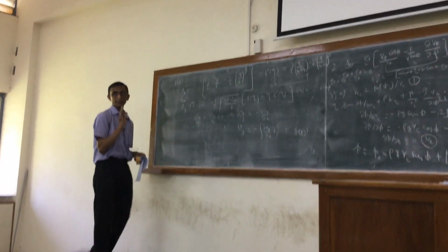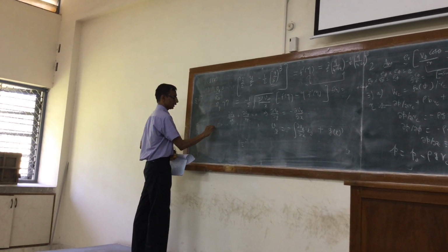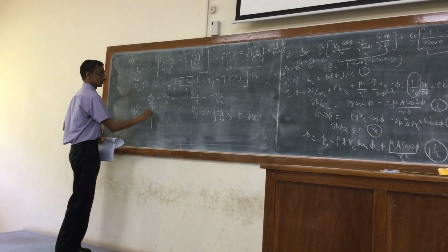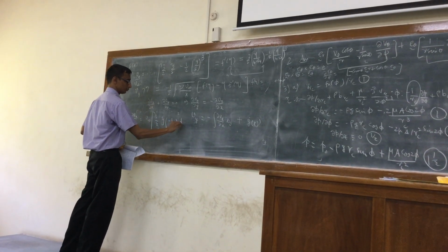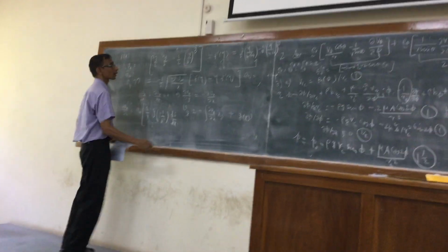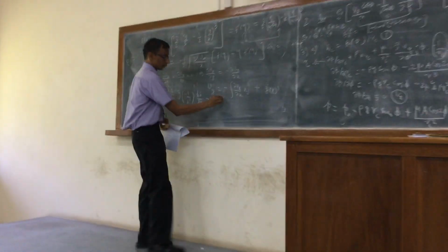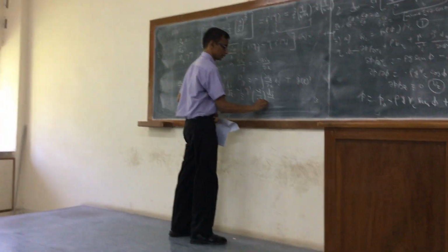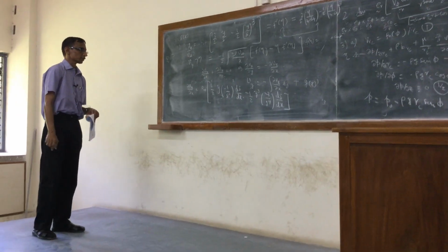So all I have to do is to differentiate this first with respect to x. So dVx by dx is simply V infinity times 3 by 2 y times minus 1 over delta squared d delta by dx, minus half y cubed times minus 3 by delta to the power 4 d delta by dx. That's all there is to it.